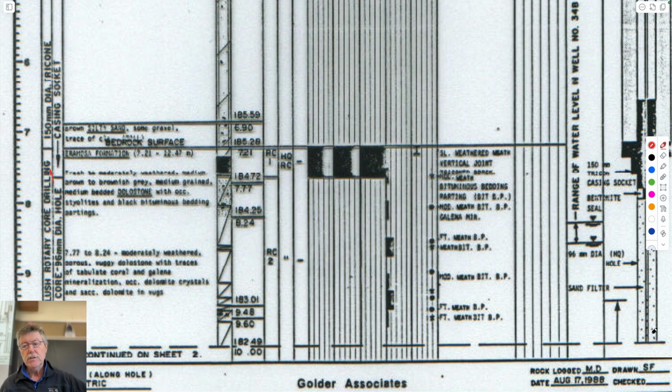And this would allow water to rise up into this tube to whatever the water level would be in the groundwater. So this is your piezometer sample. Very rudimentary, but allows you to be able to blow water out of it to get a water quality sample as well as just the water level.